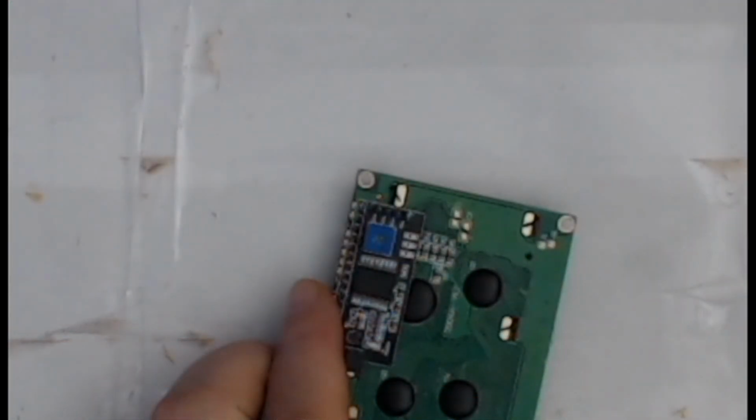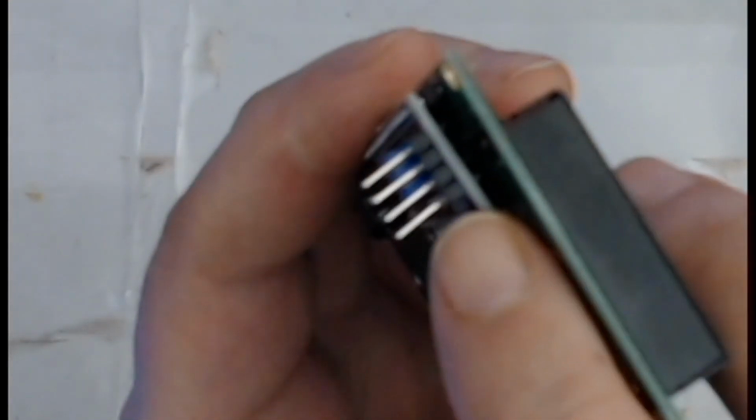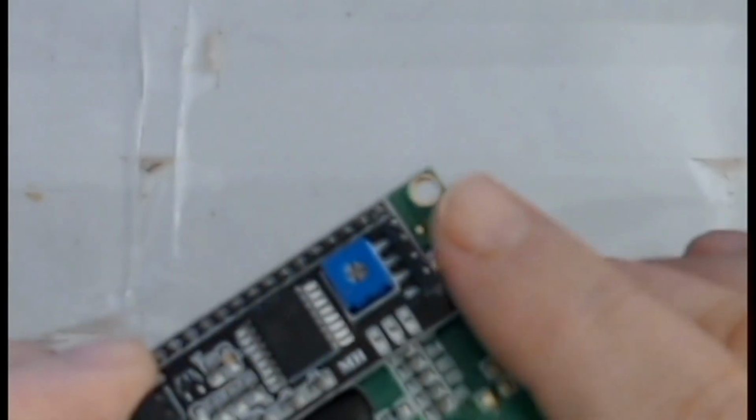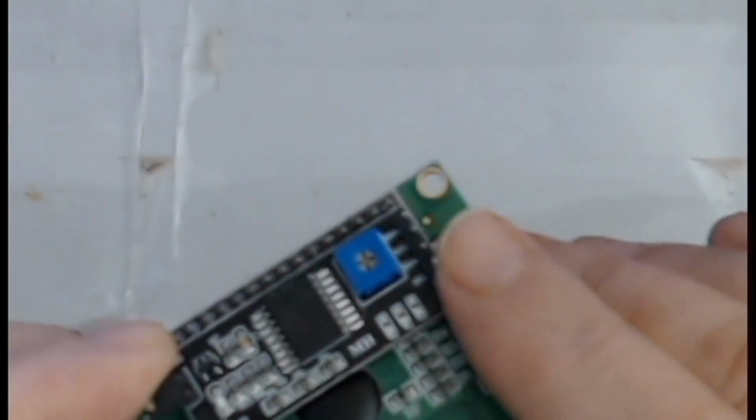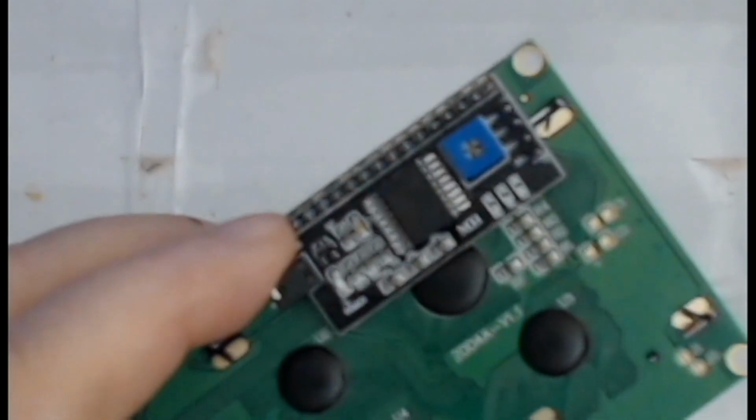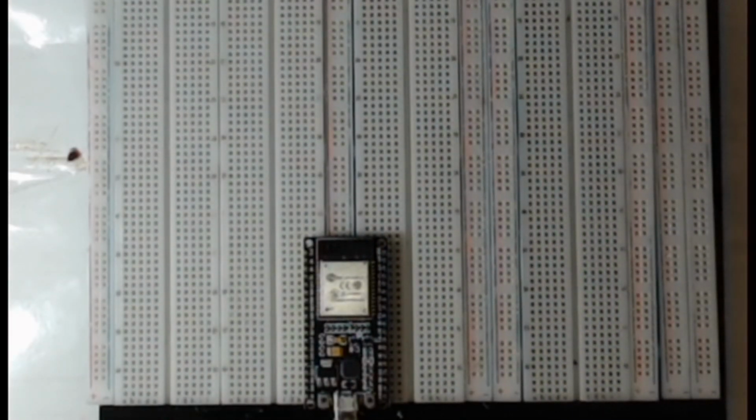This is the LCD we will be using. You will notice that we bent the pins straight. The reason for this is that it makes it easier to plug into the breadboard. Another reason is that I want to make this project modular. I want every part that goes bad to be able to just unplug the bad part, and plug the new part in. Now we are going to put everything together.